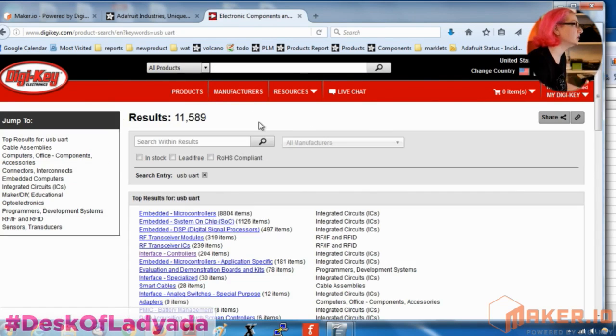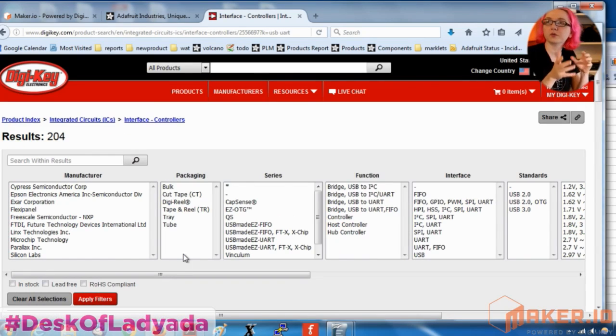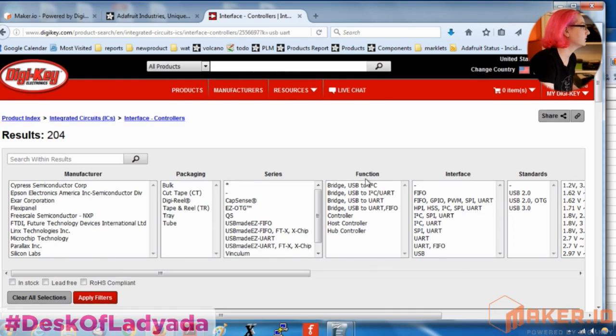A couple ways you can do it. You can use a dedicated chip, or you can use a USB microcontroller and have a sub microcontroller. For example, the micro:bit uses an NRF51822, and then it uses an mbed LPC11U24 or something to act as the mbed interface, which also does USB to serial.